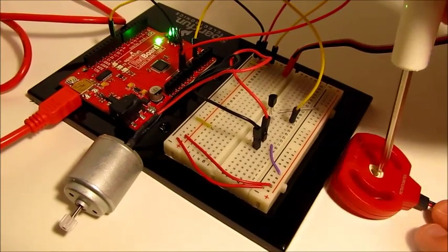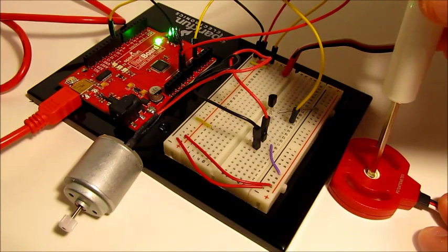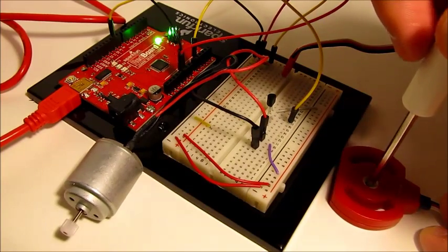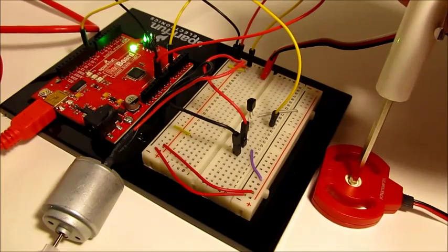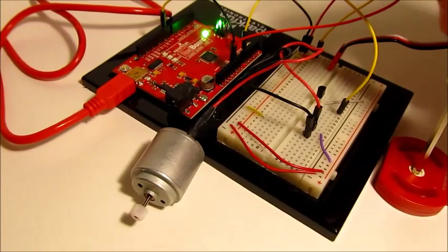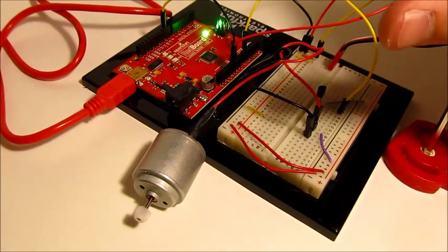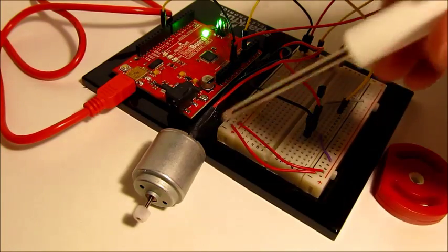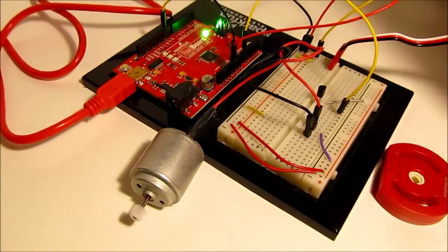But if we turn this up using the potentiometer, it starts right up, and we can turn it all the way up to the maximum speed. But now that it's moving, there isn't that stall current needed to get it going. So when we turn this back down all the way, the smallest amount of current that we can supply when the potentiometer is at its minimum is enough to keep the motor spinning and it doesn't stall out.